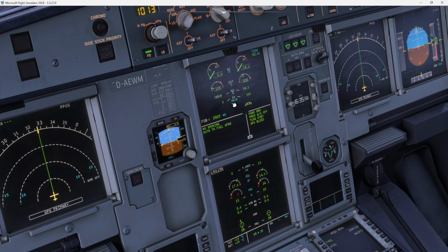At 22 we see fuel flow, and this one. If not at 22 we abort. Okay, fuel flow and N1 rising, and oil pressure is rising also. So we keep monitoring. EGT also rising. And the valve is open, don't forget.